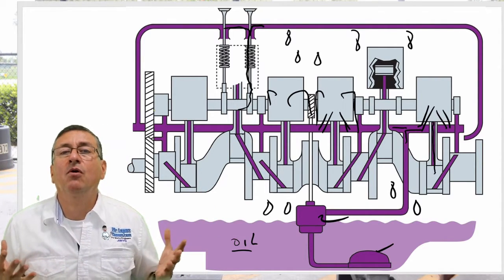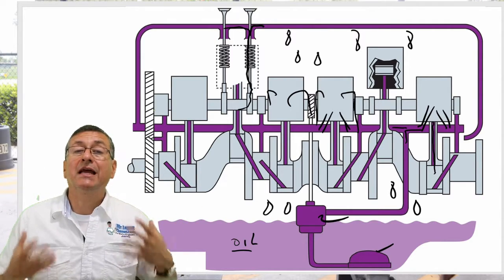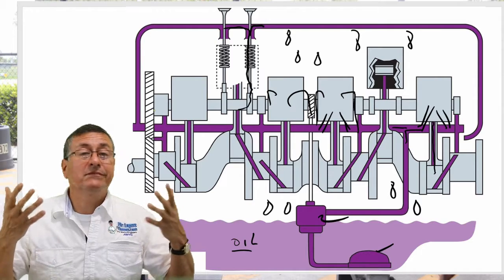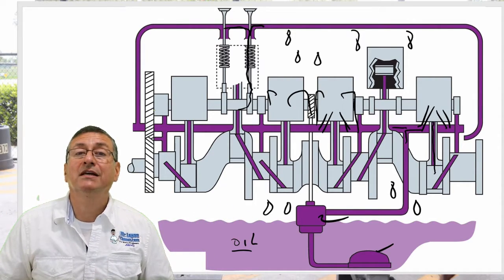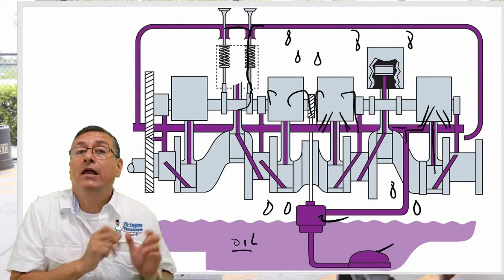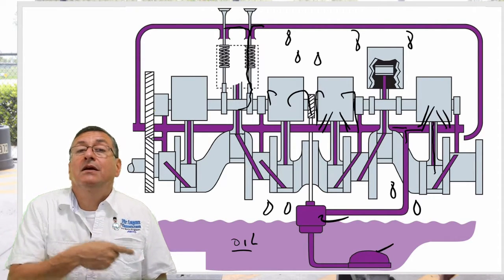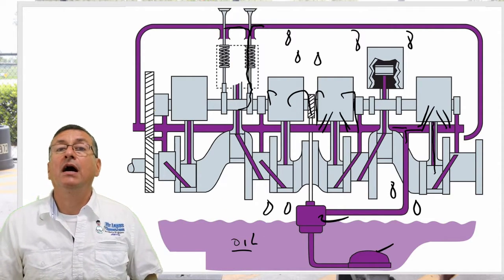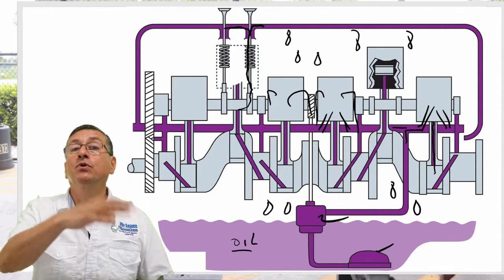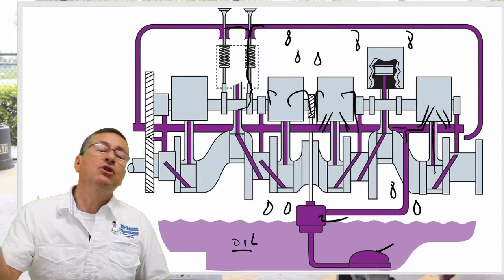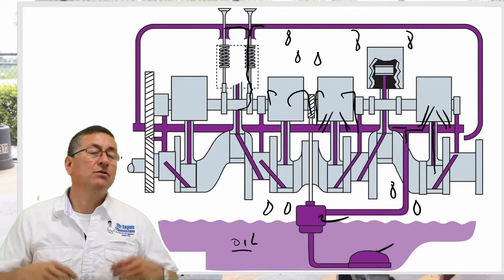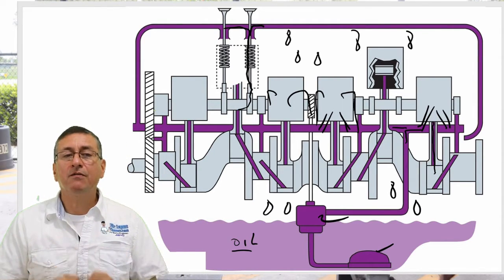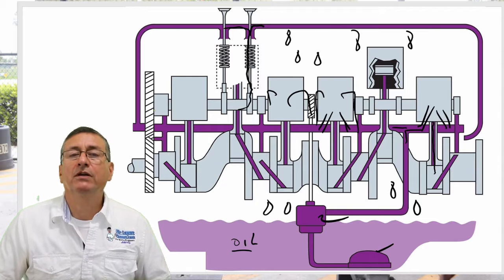Why is the appropriate oil important? Because the seals, the gaskets, the material, you remember, the neoprene, the different materials used for those gaskets are chosen according to the oil. Okay, the gaskets, the O-rings, the seals for those engines are for mineral oil. If you put in full synthetic oil, you destroy those O-rings, those seals, and you have a lot of leaks, low compression, and the engine is finito. Alright? Be careful with that and follow the manufacturer's recommendation.